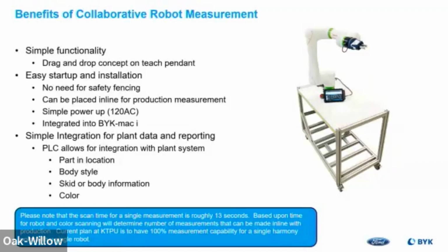We have picked the rear fender because we do a massive part replacement project here. I want to make sure that what we see on the outside is exactly what we recorded. That way we avoid any panel exchange, because the quarter panel is part of the entire body, and therefore that cannot be changed out.